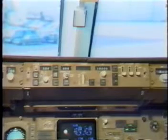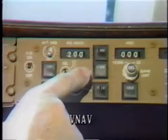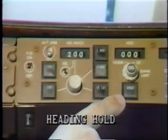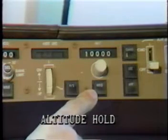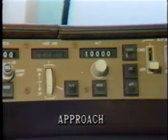AFDS modes available from the Mode Control Panel, or MCP, are LNAV, VNAV, Flight Level Change, Heading Hold, Heading Select, Vertical Speed, Altitude Hold, Localizer and Approach, which is a combined localizer and glide slope mode.